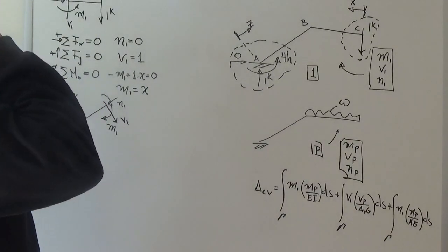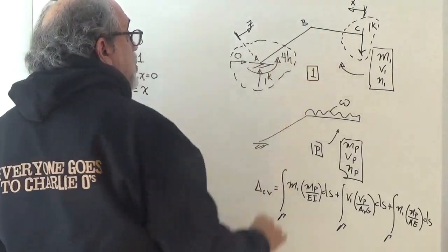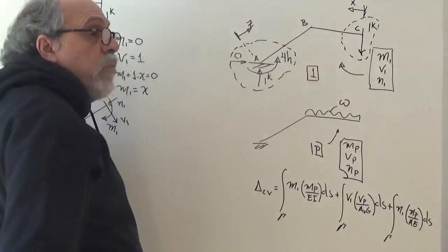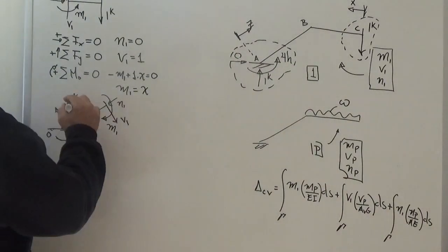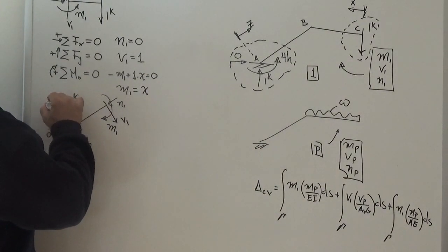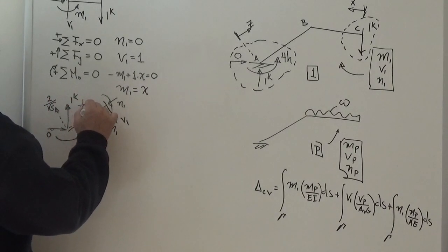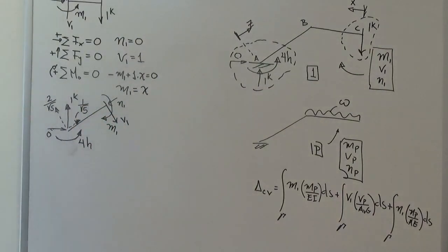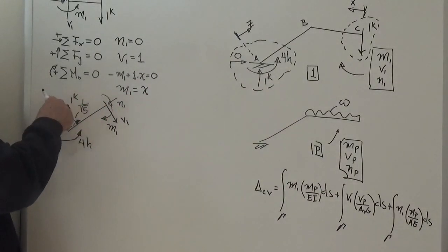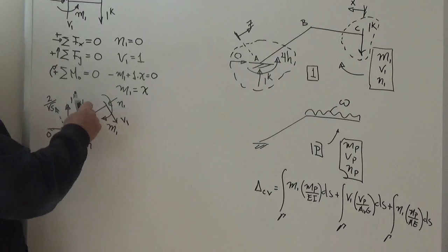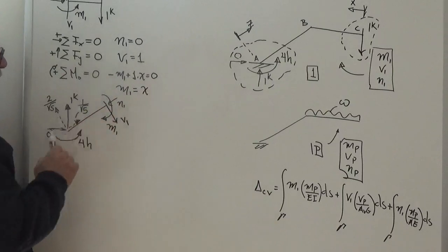So this bar inclination is 1 in height, 1 in the vertical, 2 in the horizontal. So its length is square root of 5h, right? And you can, from elementary trig, convince yourself that this component is 2 over square root of 5, and this component is 1 over square root of 5 of that load. So we have this reaction of 1 going into 1 over square root of 5 and 2 over square root of 5. And then we have a moment of 4h, no horizontal, and we have shear, axial, and moment.